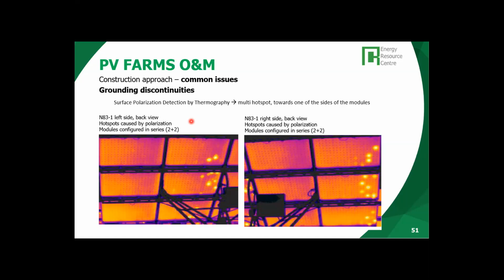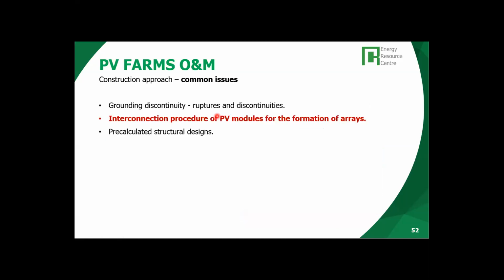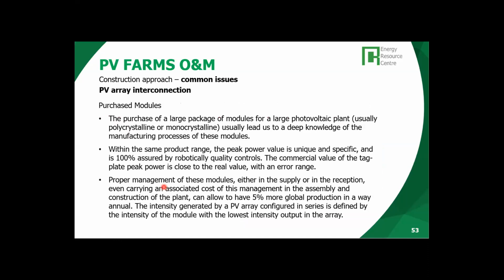Yeah. And as you say, it's interesting. Of course, you can only correct this either by changing the panels or by changing the earthing, which is very costly, very difficult. So the smart way they found in this project was to inject this inverse current through the DC lines to prevent this leakage that was reaching up to 5%. So, reacting in front of some issues. Okay, another aspect, the strings, the connection of the PV modules.